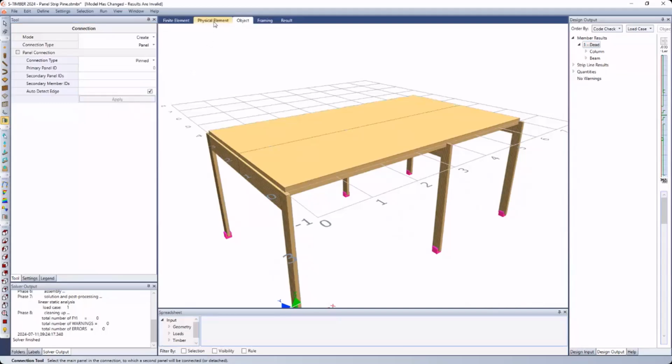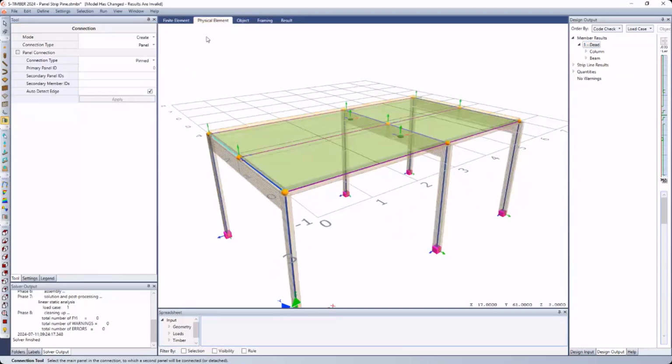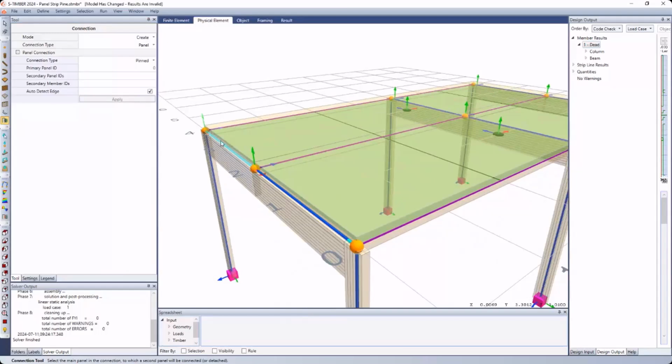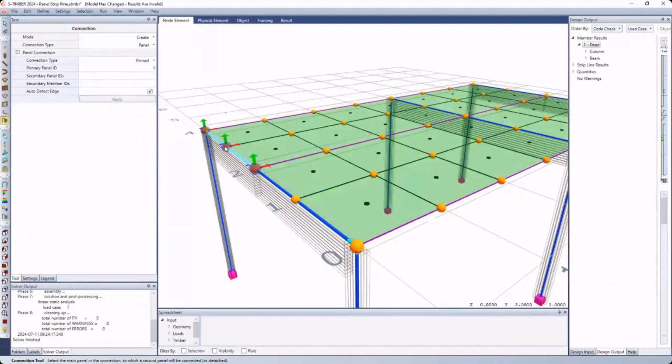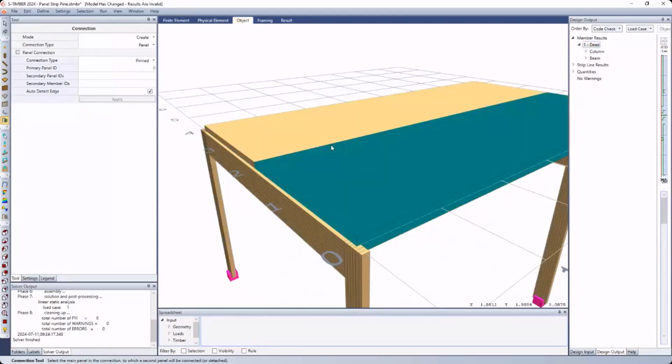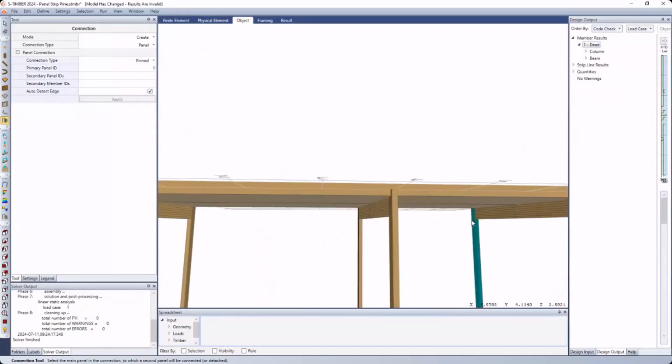And it might have been subtle. You might not have noticed what happened here, but if I go into the physical element view, we can see that there's a little blue line indicating that something's changed about this particular member. And I can go to the finite element view, and I can actually see now we have these constraints that are basically saying that we've generated a duplicate set of joints to detach the rotational degrees of freedom at those specific joints in the member from the equivalent joints in the mesh. And I can continue doing that on the other members as well, just doing a similar command.